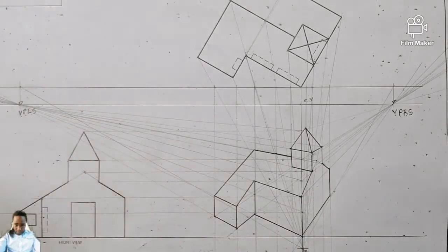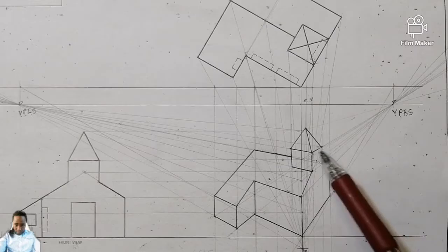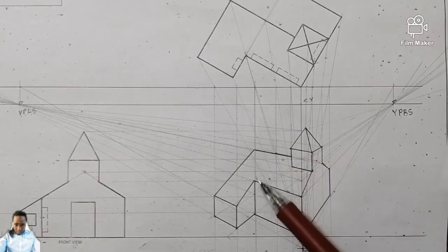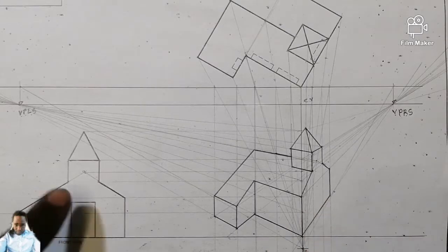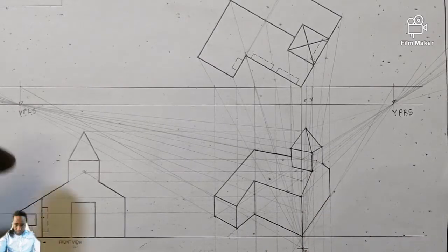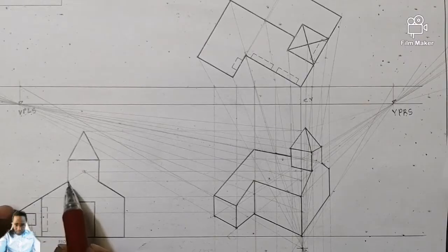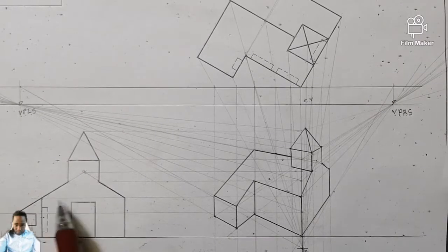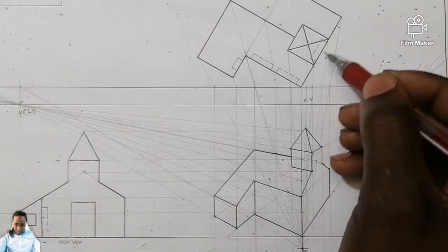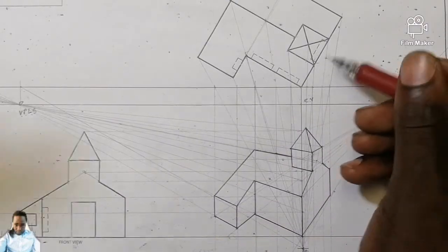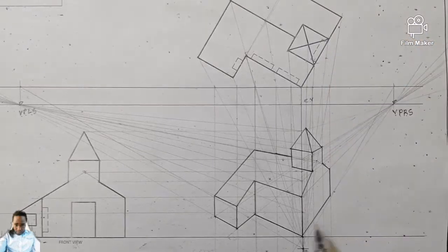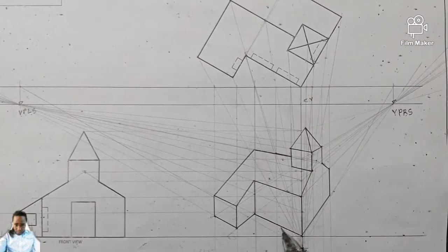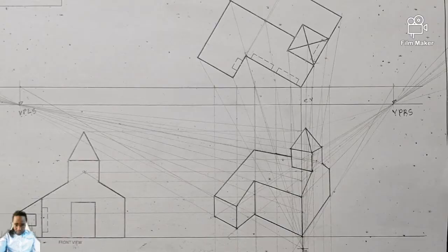So the challenging part here was how to draw this. So we had to take a very close look at how our front view is drawn. You understand? We do not have anything here, we do not have anything there, which means indeed this, and correspond it with your top view. So this is not in the center, it's actually right from this wall. You understand? So now let's put the doors and the windows.